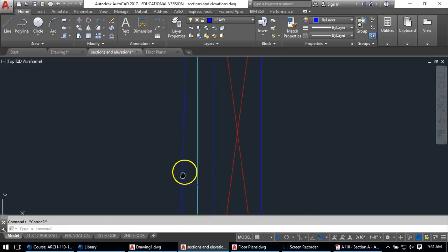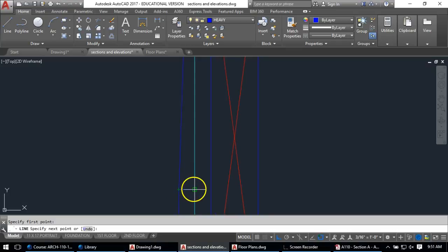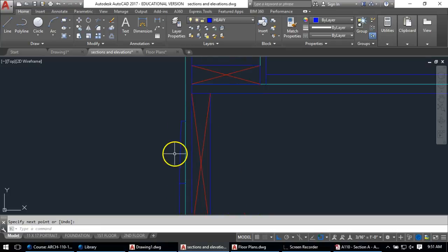And actually, what I should have done, because I'm going to make a bunch of copies of these, is I could have made this line and this line all sort of a polyline. So I'm going to key edit, say turn that into a polyline, yes. Okay, J for join. Select these 3 lines, so they become one object.